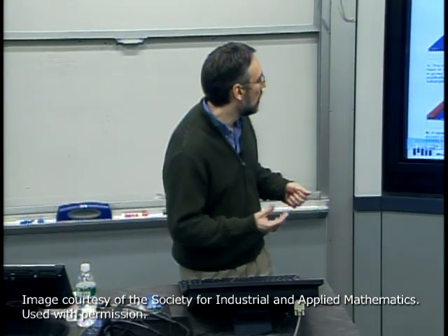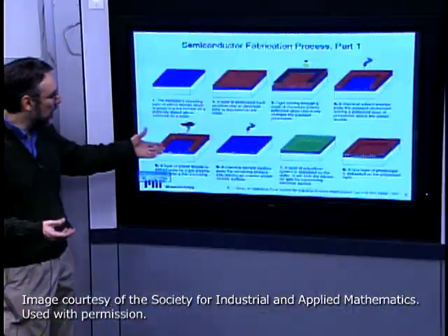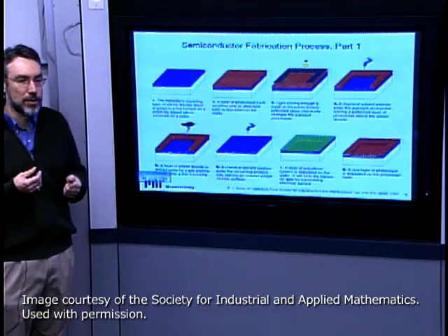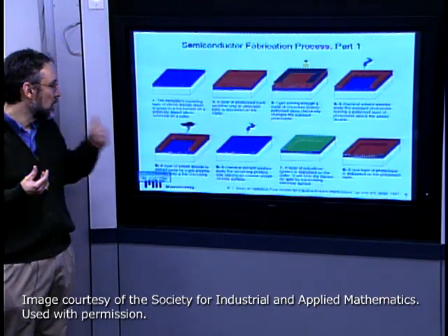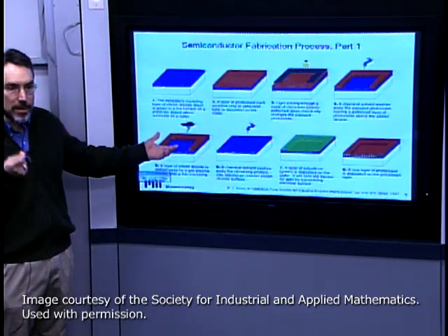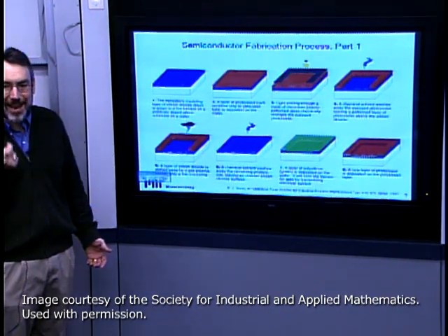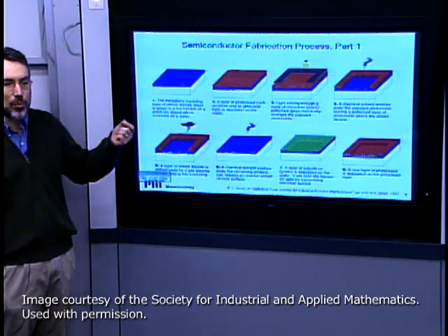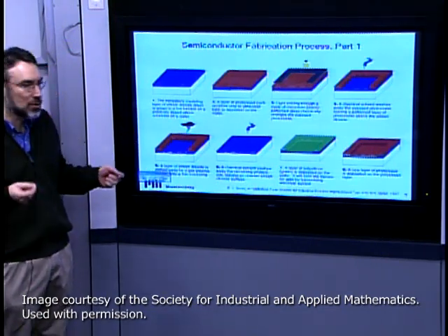So this is typically done in a very low pressure vacuum equipment where we have some feed gas. We apply RF energy to dissociate the species in the gas. Many of those species then become very highly chemically reactive and interact with the surface of the wafer and etch away particular species.